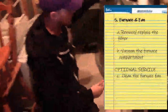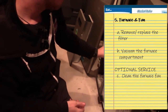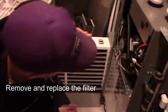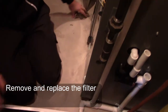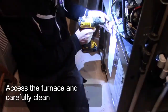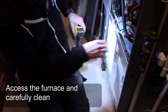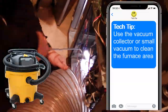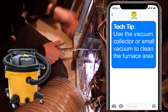Next up is the furnace and fan area. Remove and replace the filter, vacuum the furnace and compartment, clean the furnace fan. In many cases, this would be an optional service. Remove and replace the filter. Access the furnace and carefully clean. Here's another tech tip. Use a vacuum collector or a small vacuum to clean the furnace area.